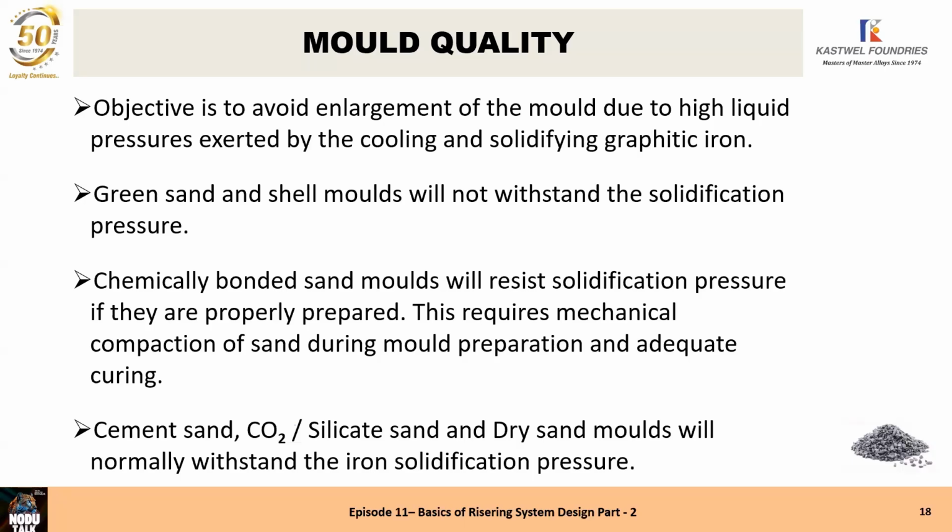Green sand and shell sand molds are not strong enough to withstand the solidification pressure. Chemically bonded sand will resist the pressure if prepared properly using mechanical compaction. And cement sand, silicate sand, dry sand are normally strong enough to withstand the solidification pressure.